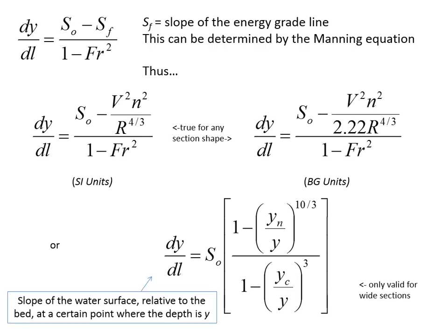Okay, so like I said, if you sometimes get stuck in a gradually varied flow problem, the first thing to do is calculate the normal depth and the critical depth. And if you're still stuck after doing that, a good thing to do would maybe be to draw a little sketch showing the depths that you just calculated. So here, what we calculated was, first of all, there was some critical depth. Y sub c, we found, was 0.2943 meters.